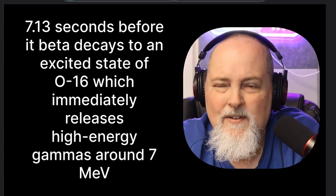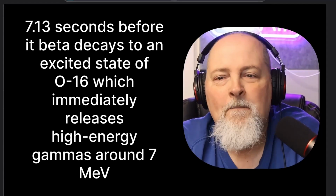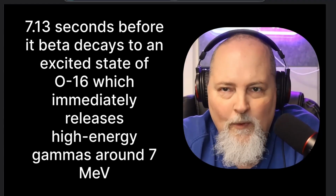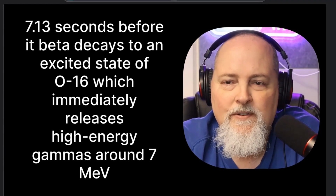That activated coolant leaves the core, moves through the piping, and it has a decay half-life of, I should have looked that up before this, like 7 seconds. Yeah, I'm pretty confident in that. 7-ish seconds. But that steam's flowing fast, so it gets all the way to the turbine, and you get that short-lived nitrogen-16 dosing outside of the reactor, outside of the primary containment. It moves through the piping before it decays, and there are other short-lived activation products.